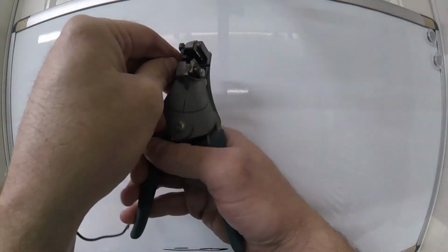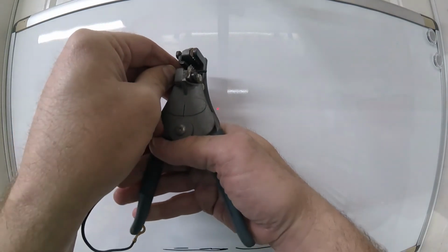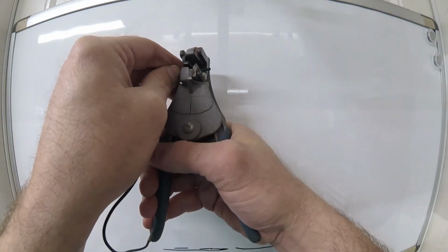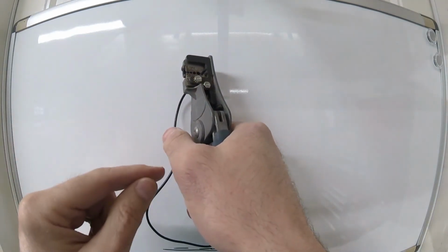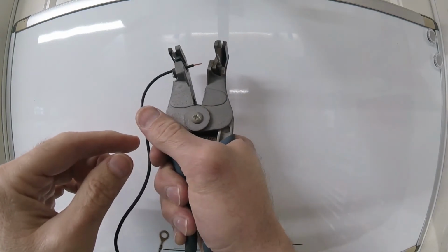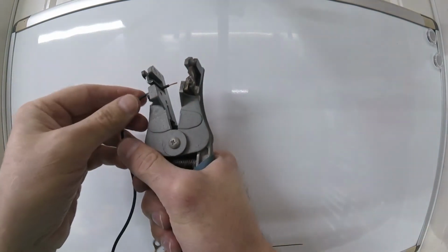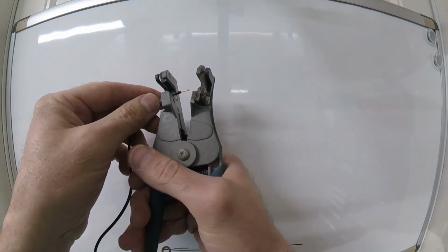And what that does is, let me find a piece of wire. Here's one. So if we put this in right, I gotta get the light right so I can see it. I believe that's going to be 18 gauge. Okay, so I stick it in like that. As I start closing and squeezing the handles, you see the clamp comes down and holds it, and then the jaw comes shut and cuts through the insulation, and as I keep squeezing, it pulls it apart. So it automatically strips the wire.